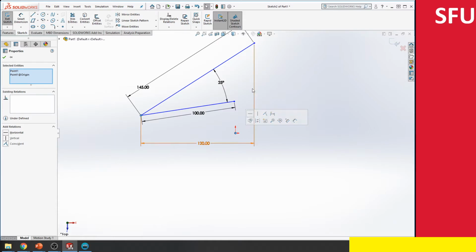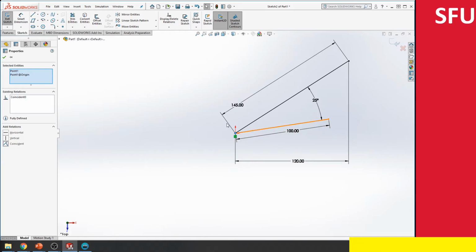I can make it vertical, where this point would get dragged here, or I can make it coincidental. Notice that as soon as I moved my mouse, I lost the context menu, but you don't have to fear that, because the context menu is still available here. So I just make it coincidental, and then now this is achieving the same objective as setting those dimensions to 0.